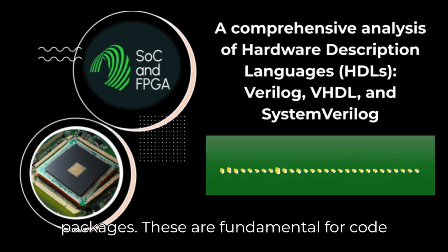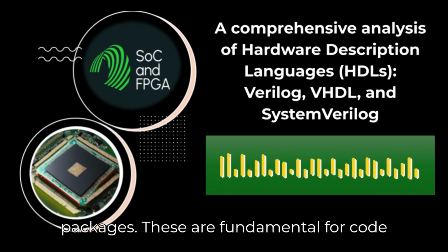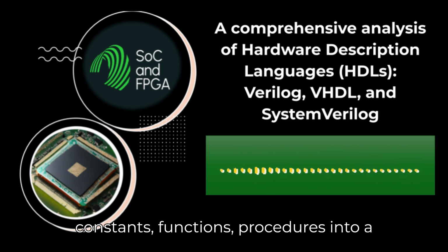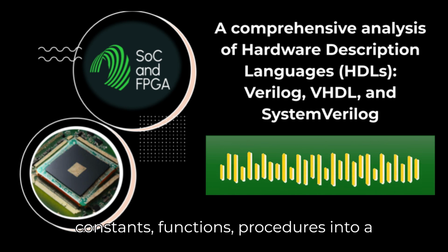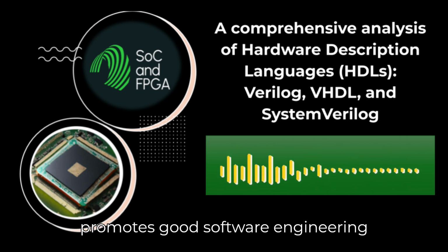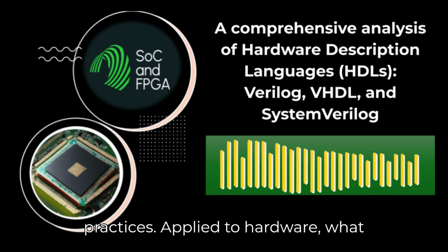VHDL also has packages. These are fundamental for code organization and reuse. You can group together common declarations, types, constants, functions, procedures into a package, and then just use that package in different parts of your design. It promotes good software engineering practices applied to hardware.